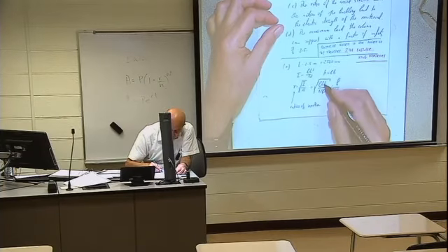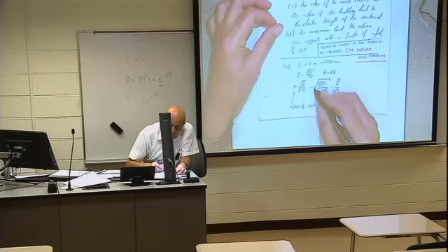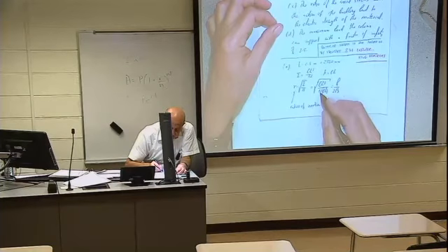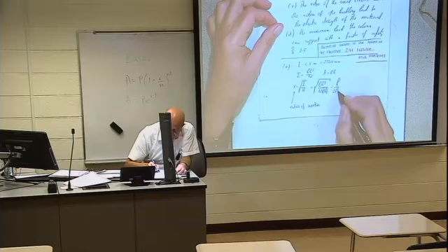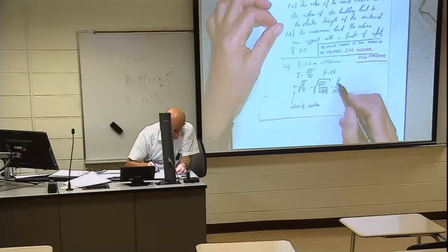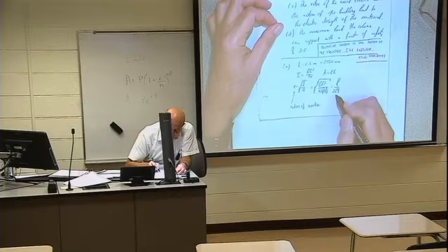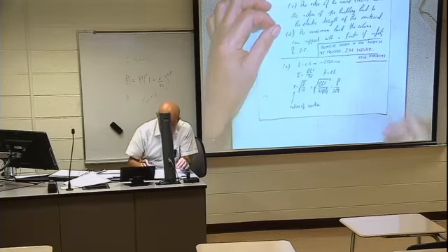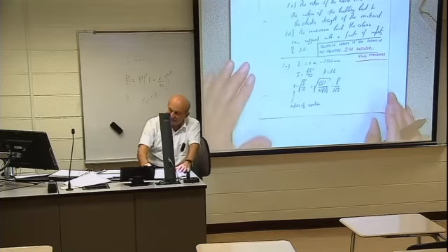We get H cubed divided by H, which will be H squared. Square root of H squared is H. So 12 equals 4 times 3. Square root of 4 is 2. Square root of 3 is staying here. So radius of inertia equals H divided by 2 square root of 3. Any questions here?